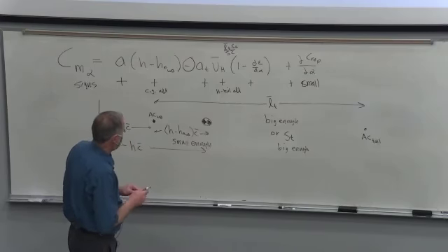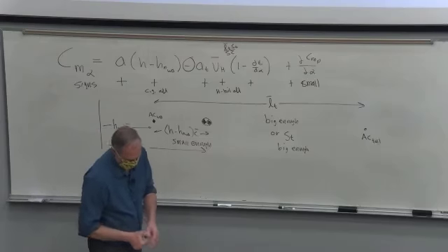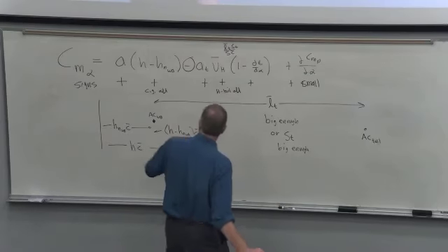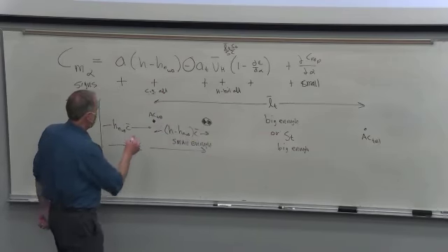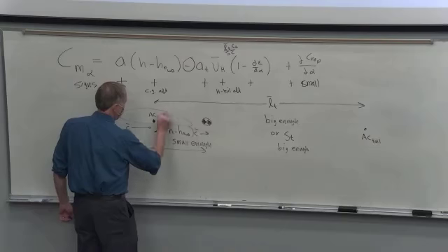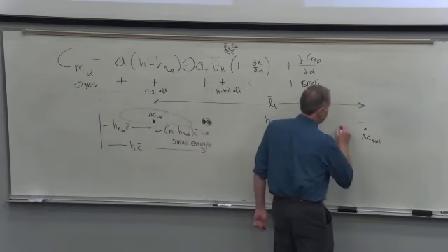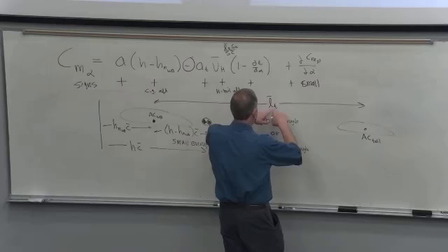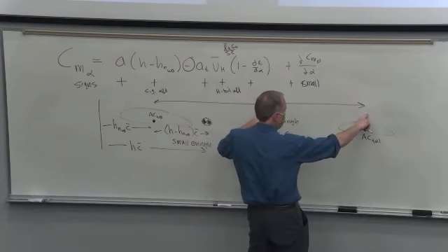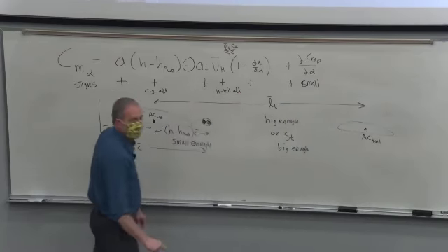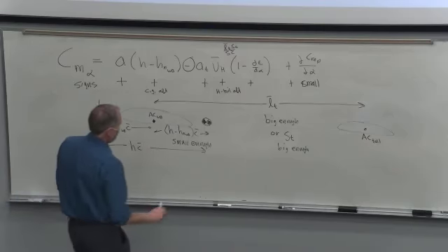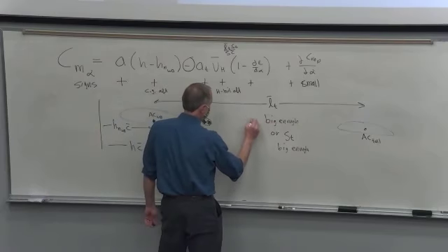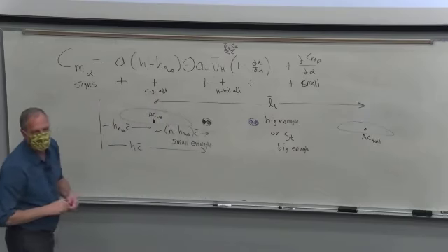Now, if you look at this, we're talking about making the CG close enough up here and the tail big enough. So let's say we've already designed our airplane like this. And here's our tail. So we've picked our tail area. We've picked LT bar, put it way back here so that we're stable. And we're good. And then we add a bunch of weight to the back of the airplane and we shift the CG back. Can it get unstable?